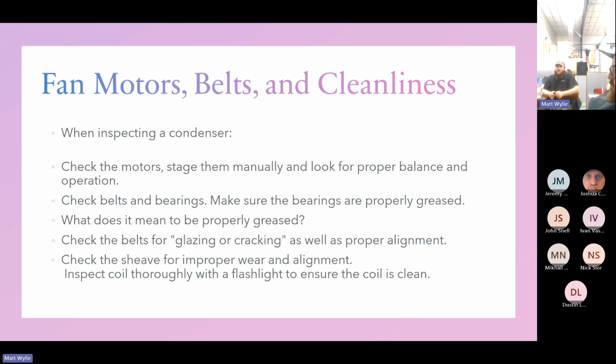Yeah. It's basically just a second small TXV that, as the compressor gets hot, sends liquid into the compressor body. I've seen two different types, really. I think the older type is usually a sensor that goes in the top of the compressor, then there's a solenoid valve. When the compressor reaches a certain temperature on the head, it energizes the solenoid and meters in a small amount of refrigerant. All the new ones, though, have switched to an expansion valve, where your sensing bulb is now in the head. You don't need the solenoid. Some of them have the solenoid, some of them don't.